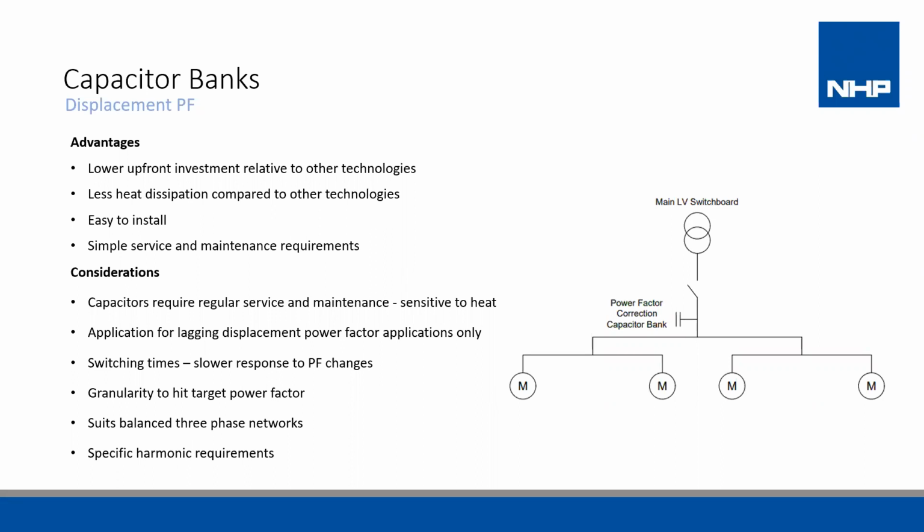For most capacitor banks, the connecting system also must be typically under 20% of harmonic current, or THDI, as we mentioned earlier. So it's also good practice to check with the respective manufacturer's recommendation on what their PFC equipment's harmonic limits or distortion limits are. So site harmonics must be taken into consideration.